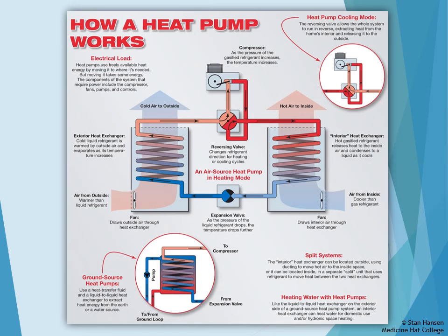Before you continue on, make sure you really understand the principles behind how an air conditioner can cool a house, because our next topic, being a heat pump, uses the exact same principles, just in a reverse direction. A heat pump is an AC system that can deliver either heating or cooling, and it reverses the refrigerant flow for heating, so the outdoor coil will become the evaporator, and the indoor coil now becomes the condenser.